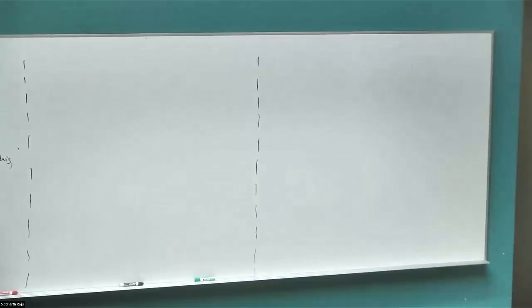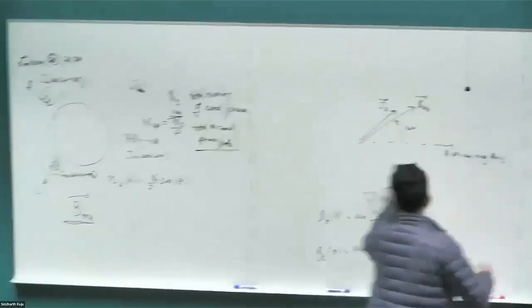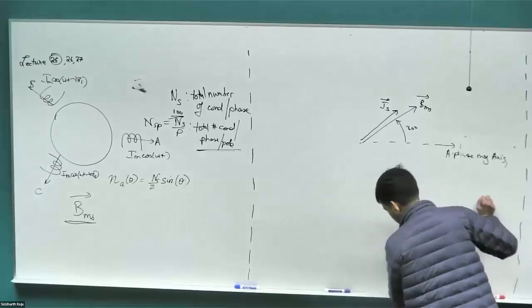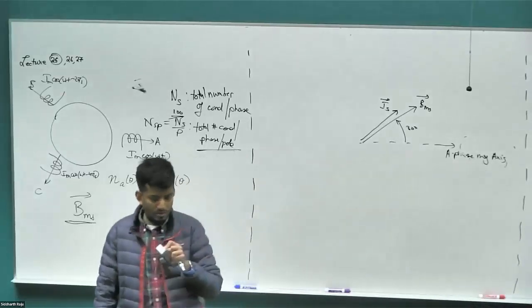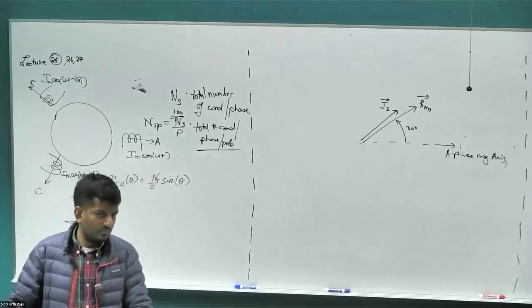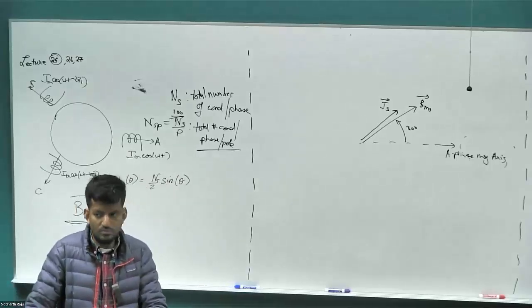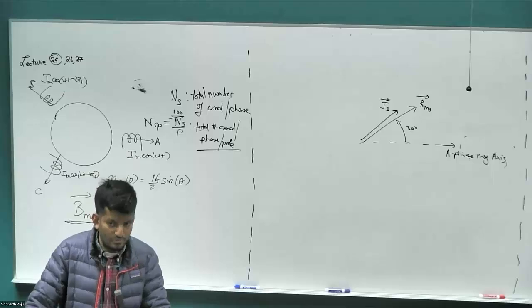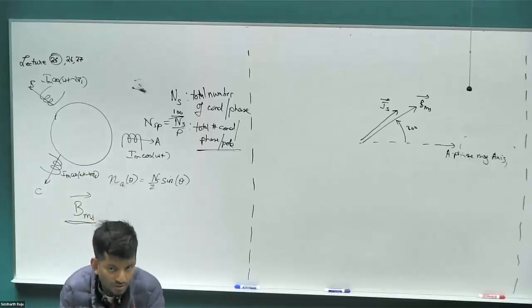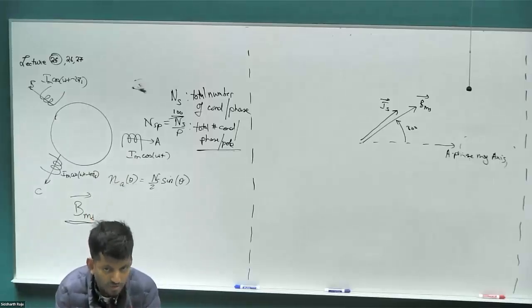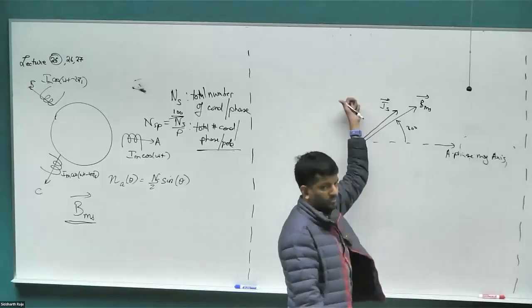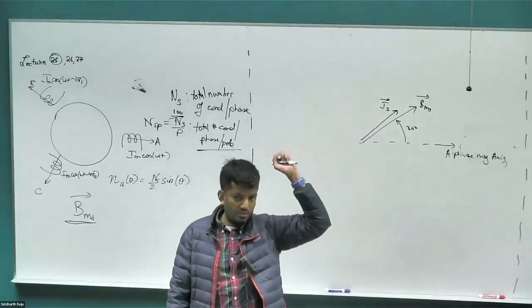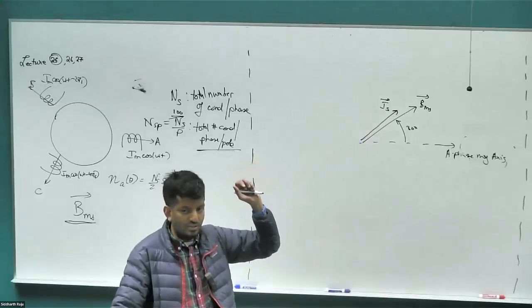Okay, where is the rotor space vector going to be? Rotor magnetic field space vector. Yep, Lily. Well, we have to know the load angle, and then it will be the load angle from B_MS. Perfect. Will it be behind or ahead? It'd be lagging behind.